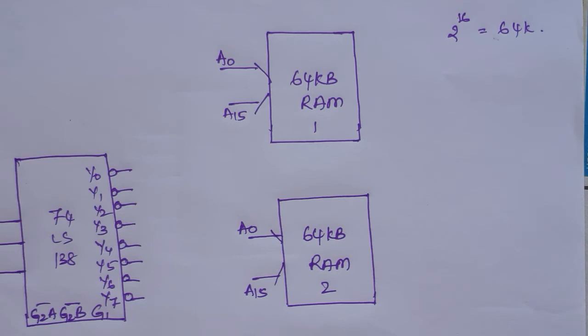It has 20-bit address lines, but data lines are only D0 to D7. Only 1 byte of data it can process at a time. So this you can consider for the 8088 processor, or any byte organized processor like 8085 where only the data bus is D0 to D7, or a microcontroller where only an 8-bit data bus D0 to D7 is there.